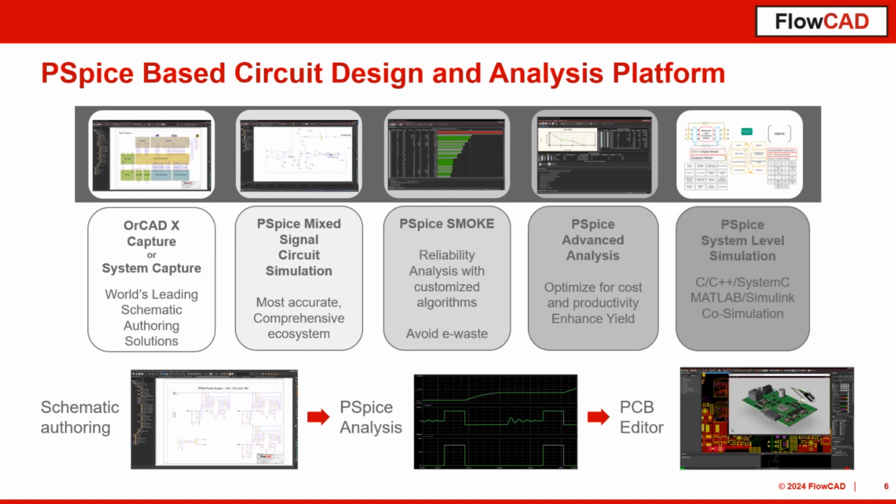PSpice is not just a single point tool, not just a circuit simulator, but it's integrated in the whole design flow. There's a tight link between the schematic authoring tool, Capture, and PSpice, and also between Capture and the PCB editor.